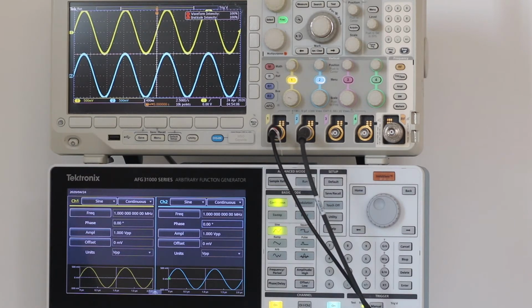to be speaking of a change that takes place over time, or a change in some condition, such as with and without a specific load. For example, the current waveform lags behind the applied voltage waveform when the load is inductive, and the current waveform leads the applied voltage waveform when the load is capacitive. That is because reactance in a circuit is a function of the rate of change in voltage, not the actual voltage level.